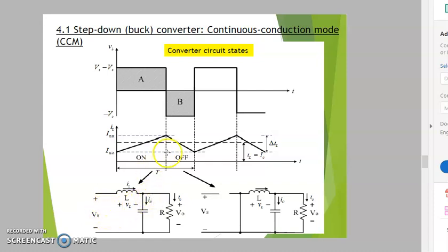But when reverse biased, it means that the current flows here to the circuit for on time, and for off time the path is taken out, so the current will also flow here, and it will not go back to the source because the switch is already open. So we will return to the load through the diode here. The place of the diode is visualized as a short circuit. So still you have a current that flows into your load.